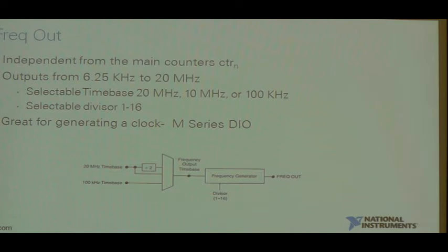Many people don't think to use it as a trigger because it's a pulse train, not a single pulse. But we're just looking for the first edge, so it doesn't really matter in most use cases if we continue to toggle that line after we've received our trigger.